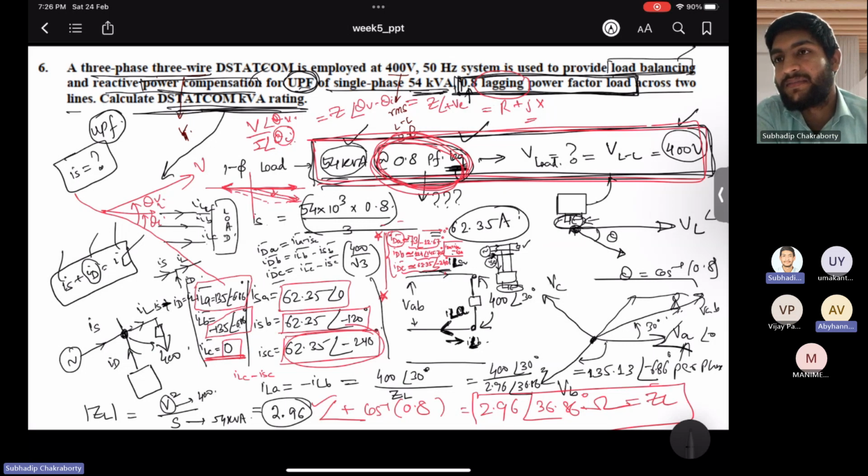Understood, sir. Only doubt is the source of this active power in this DC link. Where exactly, you mentioned batteries? Is it in the control system of the DSTATCOM, or in the primary? Control is only signal conditioning. Actually there is a source sitting there. What you will control is the DC link voltage. What that means is that the charge coming into the capacitor should be equal to the charge coming out of the capacitor. Then only the voltage remains constant.